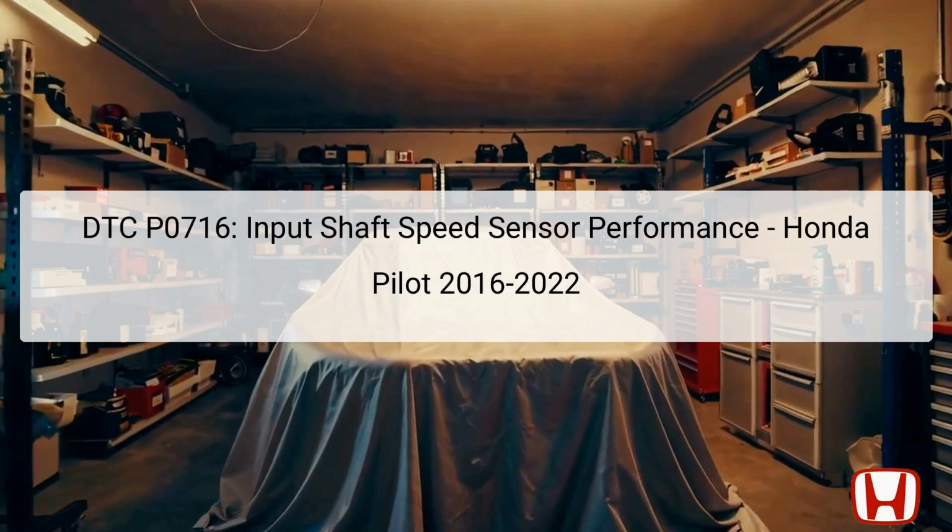The DTC code P0716 pertains to the input shaft, main shaft, speed sensor, and indicates a performance range issue. This error suggests that there is a problem within the electrical circuit related to the sensor, rather than a mechanical issue within the transmission. The input shaft speed sensor is a critical component that monitors the rotational speed of the input shaft, which is essential for determining optimal engine and transmission operation.